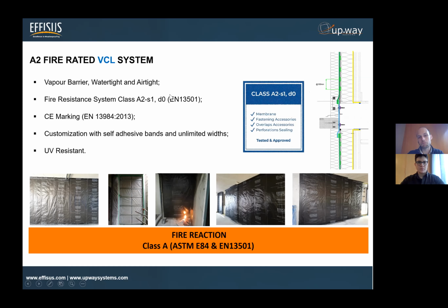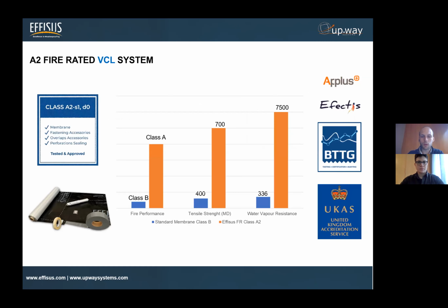And UV resistance, normally this is installed on the inside, but for instance in the Middle East it is installed on the outside, and UV resistance turns into a very, very important point. João, you already shared some things about these values, but here we can now have the support of this scheme. So you mentioned already tensile strength. This is really different from a standard membrane.